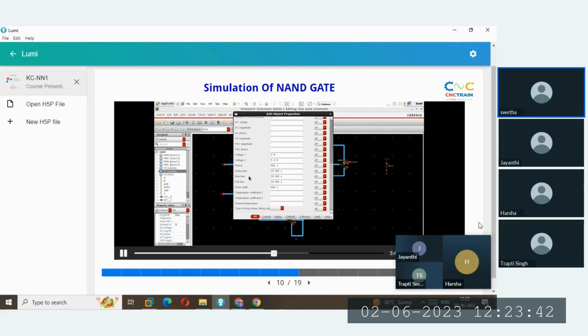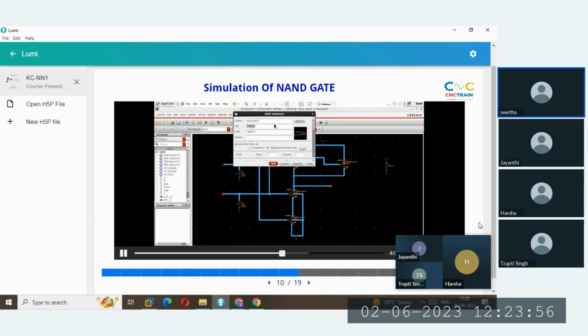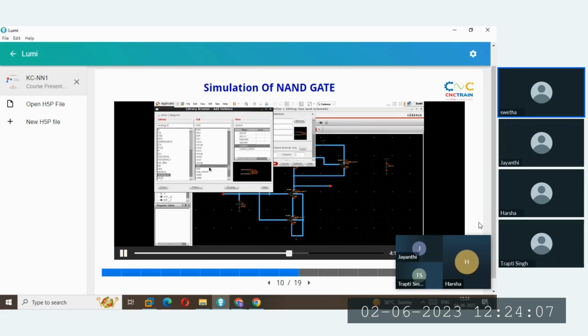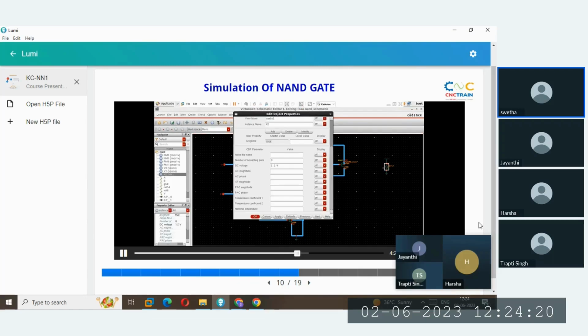After that, we need to give the VDD voltage also to run the schematic. VDD will act as a supply voltage to the circuit. For that, in the analog library, click browse here and click on VDC. Click on the VDC symbol and close. So the VDC symbol will appear. Next, give the ground and VDD for the VDC and click on the Q icon for giving the DC voltage. The voltage I have given as 1.2 volts and click on apply and OK.